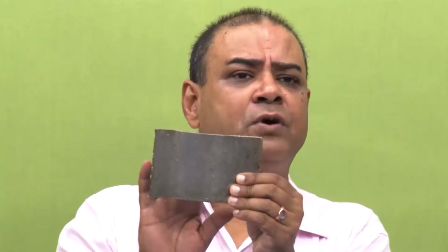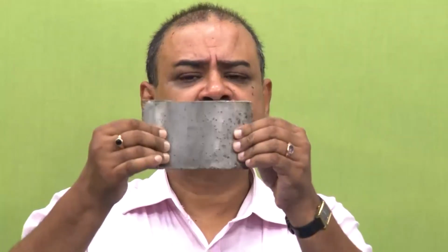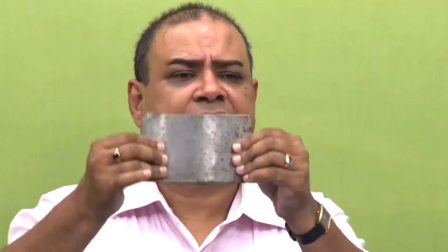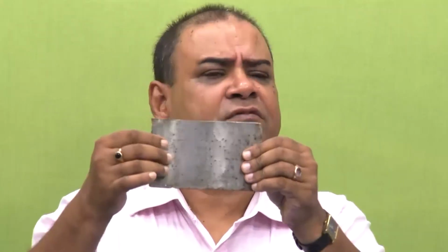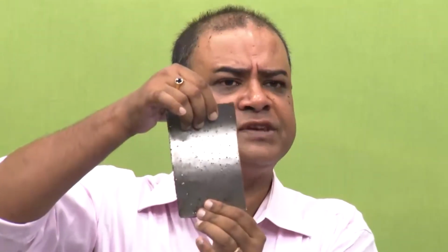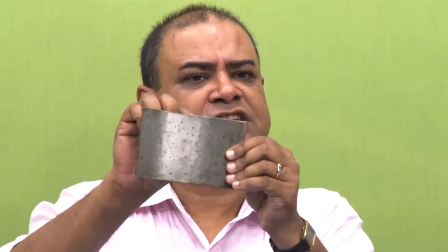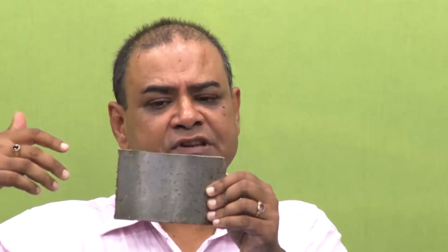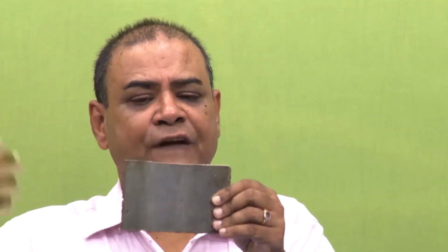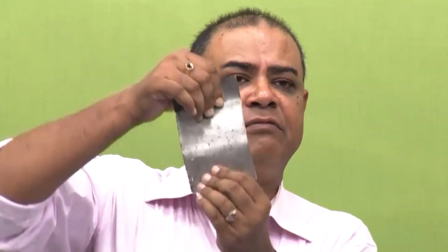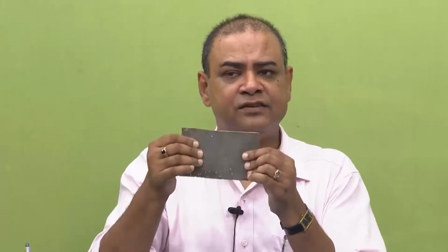So, I am just talking about a structure which is made of some kind of material like this, and these structures are designed to hold some load. Now, once we have holes like this, the cross section is decreasing. The design load will be felt heavily on these smaller cross sections, and then the stress would go beyond yield point and it will start yielding, and the situation may arise that it will crumble into pieces.